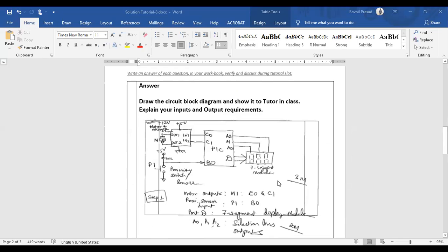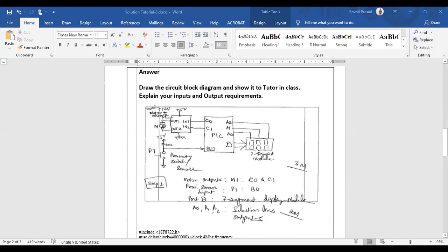We have already worked with the 7-segment display in our labs, so we all understand that we'll need 3 pins to turn the LEDs on and off, while there will be a set of ports passing the data to the particular 7-segment display we are referring to, right? So we can assume that the data pins are all port D pins, while A2, A1, and A0 are the turning on and off switches for the 7-segment displays, right?